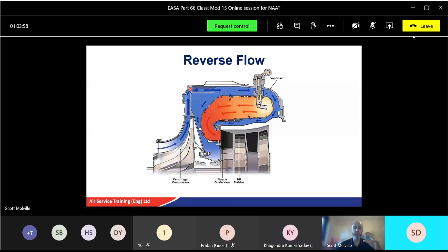So the compressor, this component, and then the combustion chamber. What was this component in between called? Diffuser. Diffuser, good, yeah. So diffuser, divergent in shape. It slows the air down, the last chance for a pressure increase.